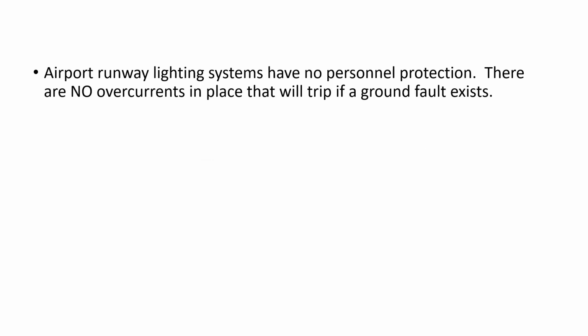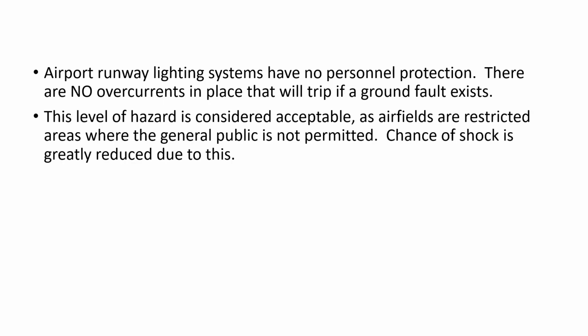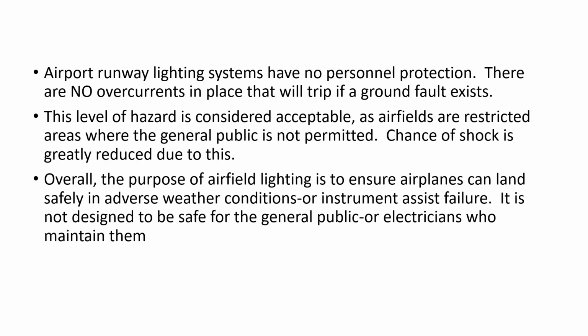Airport runway lighting systems have no personnel protections where overcurrents are concerned. No overcurrent trip if a ground fault exists. This level of hazard is considered acceptable as this is a restricted area. Overall, the purpose of airfield lighting is to ensure airplanes can land safely in adverse weather conditions or instrument assist failure. It is not designed to be safe for the general public or the electricians who maintain them.